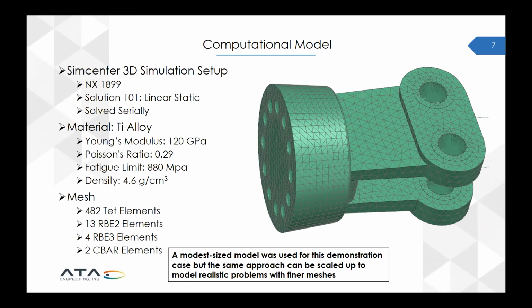We're using a titanium alloy, and here are the properties. The fatigue limit is 880 megapascals, and in our design, we're going to want to design with a factor of safety of 2 on that fatigue limit.